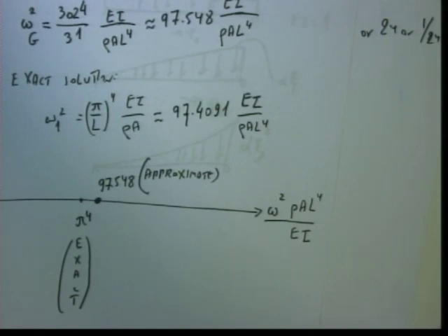Yes, in that case, the Galerkin method already will be inapplicable. We need to use some other methods. What immediately comes to mind is to use some asymptotic methods, because asymptotically, for a very high frequency, beams behave the same whether they are simply supported or clamped. The simply supported frequency is K times pi, yes?